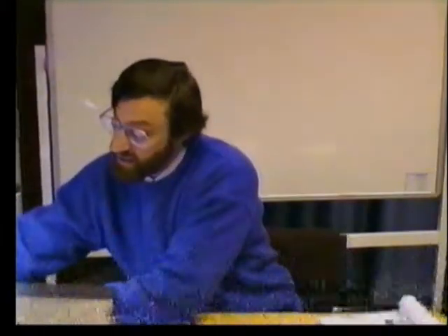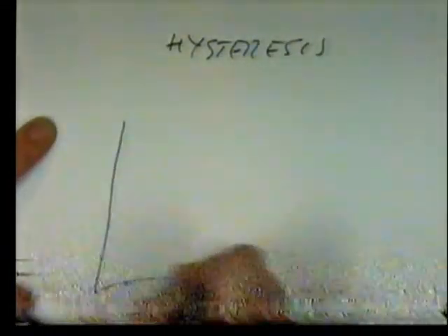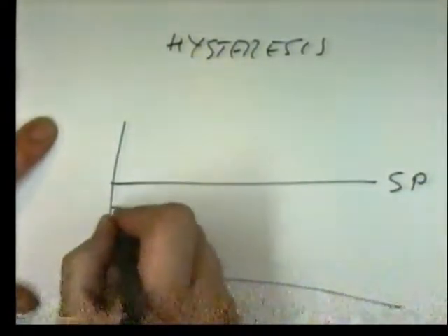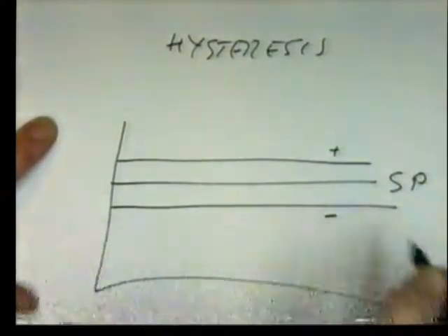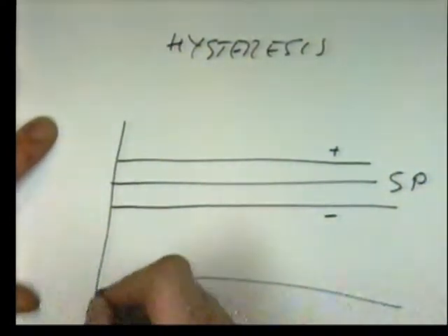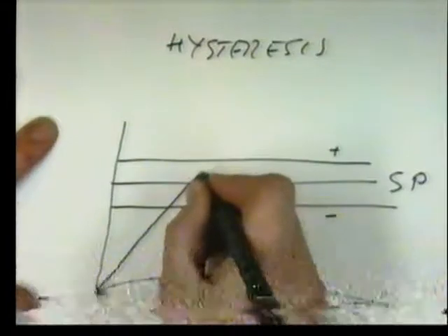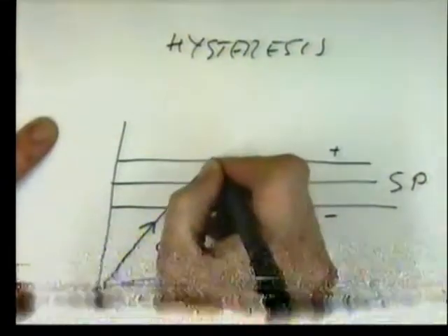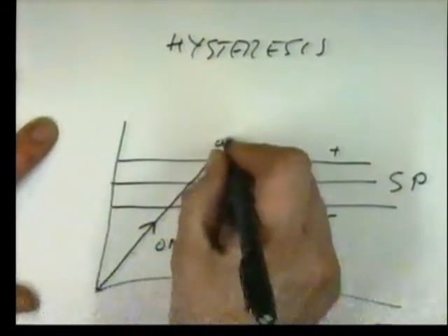So one of the techniques I showed you how to do that was hysteresis. With hysteresis, if here is our set point, and we widen the set point with a hysteresis band, a hysteresis positive, hysteresis negative. And what we said was that we would keep our system on, not just to the set point, but through it. We would let it overshoot. So while we're rising, we remain on until we go over the hysteresis band. Then, only then, do we switch off.